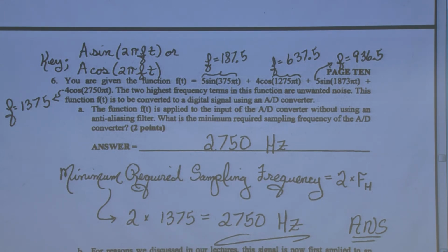Perfect. Depends if you want the cutoff to be, if you had a value of 3,000, you said I want it to cut off after... Right. 1375. Exactly. So, Chris, that's the point I get to in the next part of the problem. That's excellent. So what we say here, my colleagues, is there is no anti-aliasing filter, and as Chris is pointing out, we don't yet have the concept of a cutoff. We have nothing. We're just putting the whole thing into the A to D converter. Go to the highest frequency, which is the 4th term, 1375, double that, 2750, and we're done, part A.